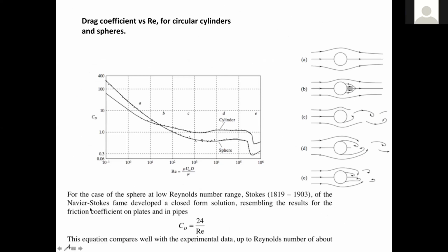I mentioned that Stokes suggested, so this is a full range of Reynolds number. We usually say high Reynolds number starts here. But he developed a formula for, this would be one, so somewhere up to here, for viscous flow, which is 24 over Reynolds. So that's for viscous flow, and we think that that formula will work. Later on, we're going to check if it's indeed correct.